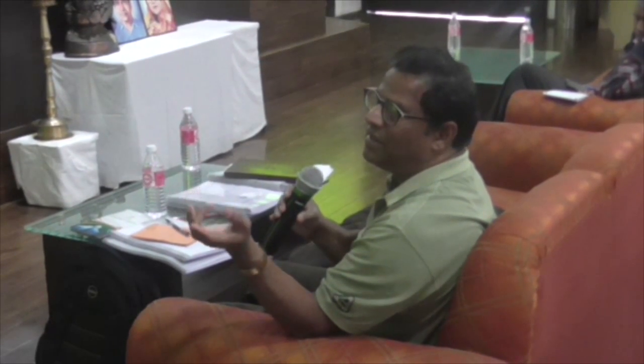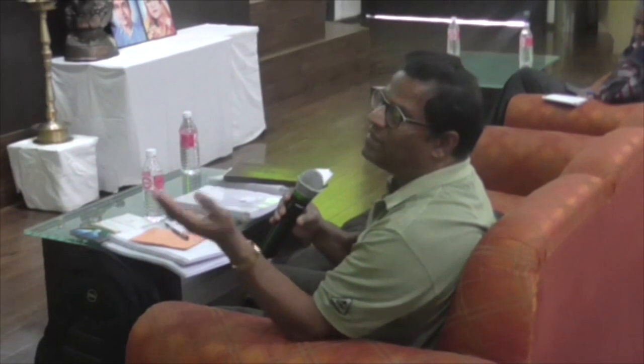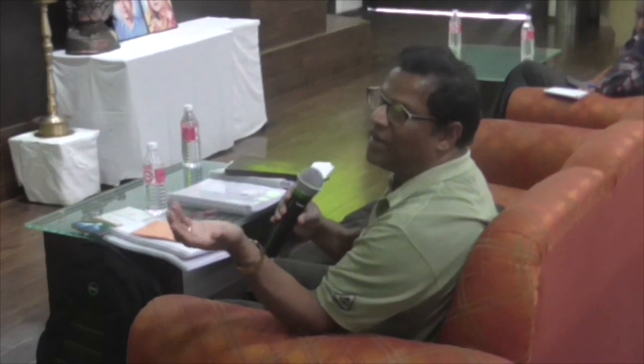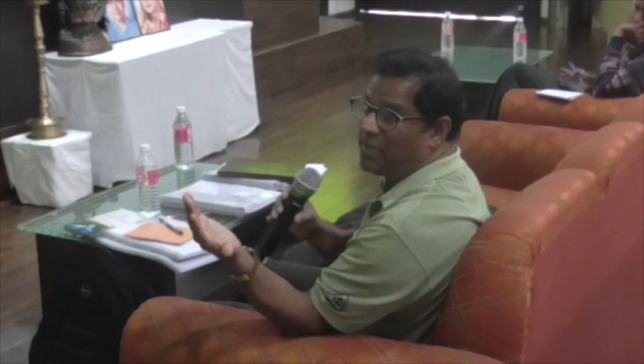Because I did not see in both of your reports what the normally occurring fluoride concentration is when water is highly polluted. Do you have any values, say from Andhra Pradesh, or areas of fluoride pollution? I have shown that. So actually, in that data, there is a minimum concentration and a maximum concentration, so I have taken an average. So what is the average? That average is near about 10 mg per liter. That's why I have kept 10. So in real life, in the field, it can go up to 10 ppm.